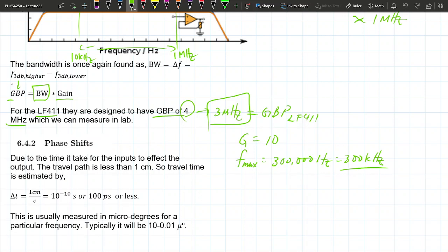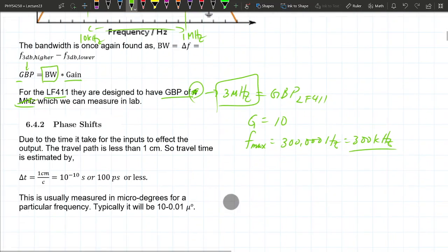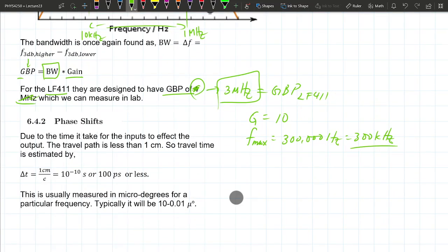Bandwidth product. A lot of times they just say bandwidth. Supply current. Okay, yeah, 3. Yeah, there's actually 3 now. Okay, so cross this 4 out. Okay, the stuff you have can usually probably do a little bit more than 3. Because the manufacturer usually makes it a little bit better than the minimum that they need to pass the spec, right? So that's what they will do. Okay, and in lab 5, you actually measure this yourself.